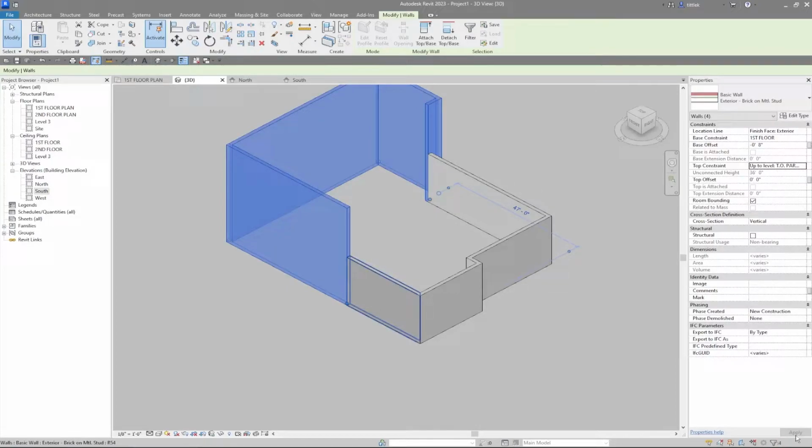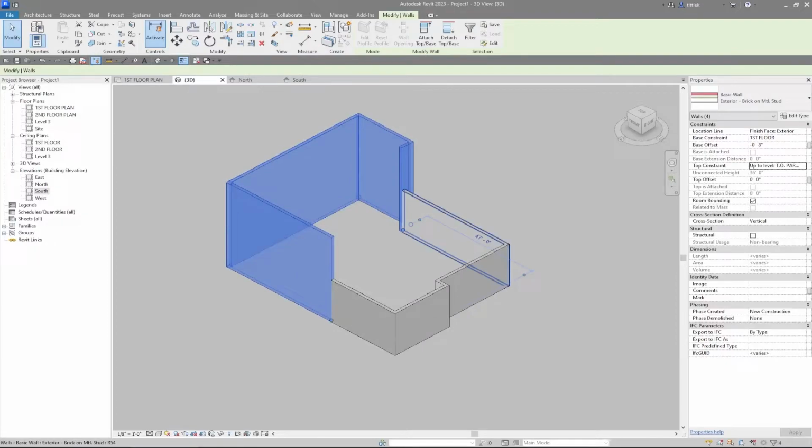You don't ever have to hit apply. Again, little quick tip, just move your cursor away from your properties window. As soon as it's off of the properties window, it'll be applied. Now you can go back and get the remaining heights of these walls correct. I'm not going to do that on screen, but I'll come back when that's done.